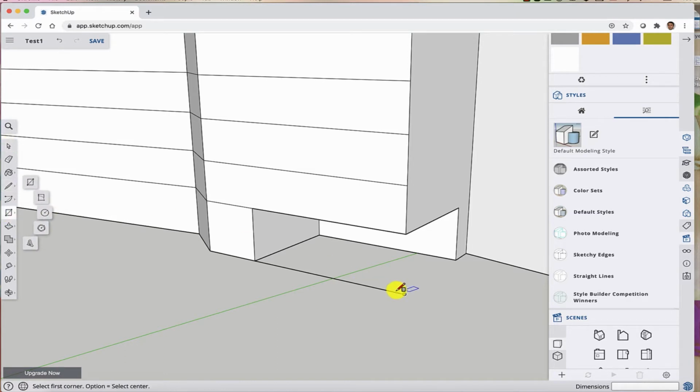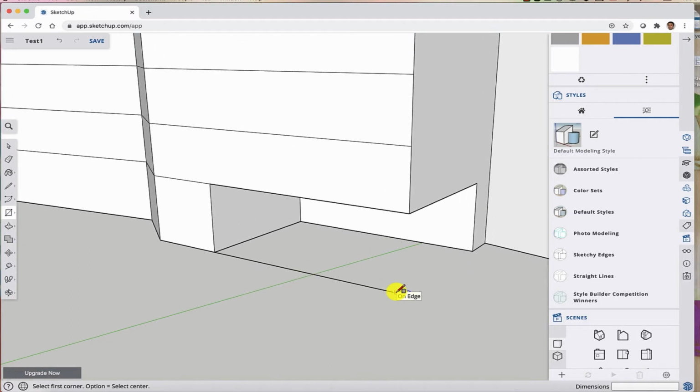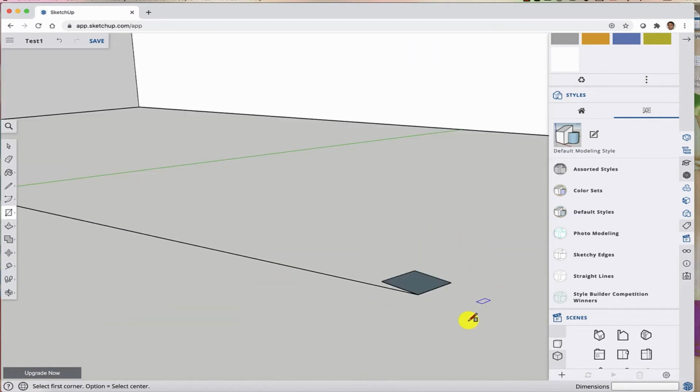I'm going to click the rectangle tool, and I'm going to type 1.2 feet, comma, 1.2 feet. Enter. So if I zoom in, okay, this 1.2 by 1.2 feet column is not completely aligned with that line. So I have to rotate this rectangle.